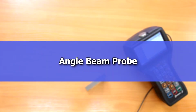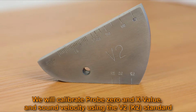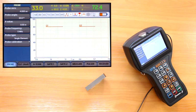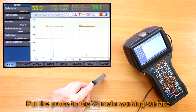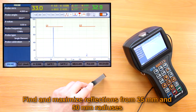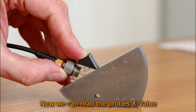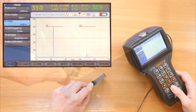Now let's see what can be done for the angle beam probe. First of all, we will calibrate its 0 and X value and sound velocity. We will use a V2 standard made from the same or at least similar material as the test object. I put the probe on the V2 main working surface, enabling its coupling, and find and maximize reflections from 25mm and 50mm radiuses. In this position, I can read the probe's X value, the distance from its front edge to the index point, 0.5 inches in this case.